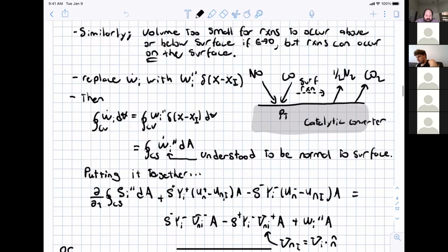So now we finished those. We discussed all kinds of things, and there are all sorts of assumptions that you can make as to how you're going to model any phase change process, such as evaporation or surface reaction. And even there are different vaporization models, and I only highlighted a few of them that are commonly used in combustion, but there are lots and lots of them. So now we conserve mass and species mass. Now we've got to do momentum.